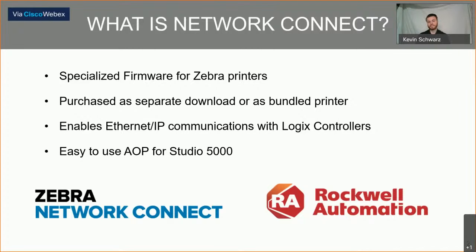NetworkConnect, in the case of printers, is a specialized firmware specifically for Zebra printers, and what it enables is Ethernet IP communications for Logix controllers, so that you can use your Ethernet printer as an I/O device in your controller organizer and under your device tree with your Logix processors.